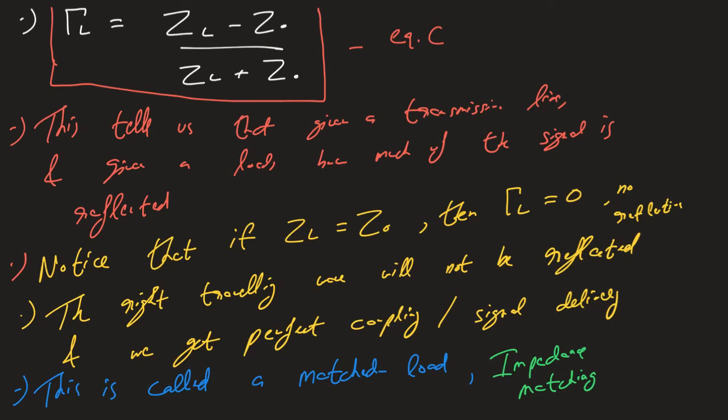Now, oftentimes, let's say you have a coaxial cable. Typically you use a lot of coaxial cables in laboratories, and a lot of times when you buy a cable, the manufacturer tells you the impedance of your cable. It's, let's say, 50 ohms or whatever, and the reason it gives you the impedance is that you want to match the impedance of your coaxial cable with the output impedance of, let's say, your function generator, and you want to match it with the input impedance of your